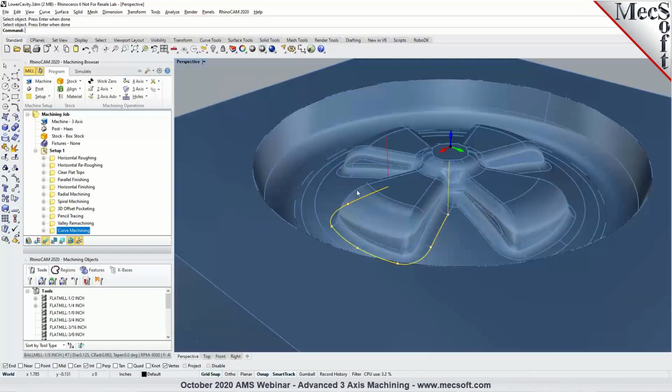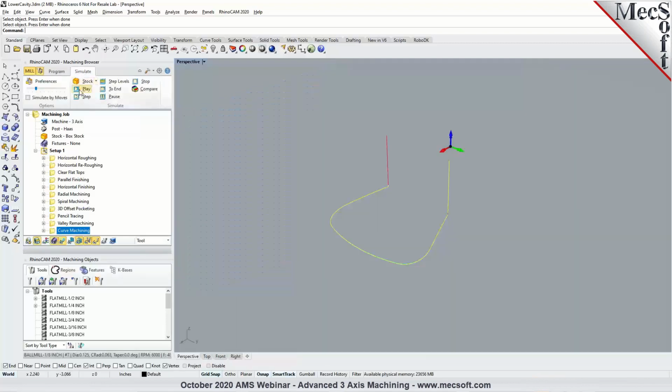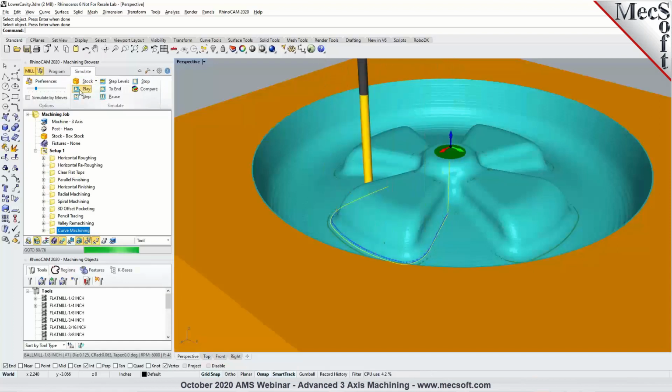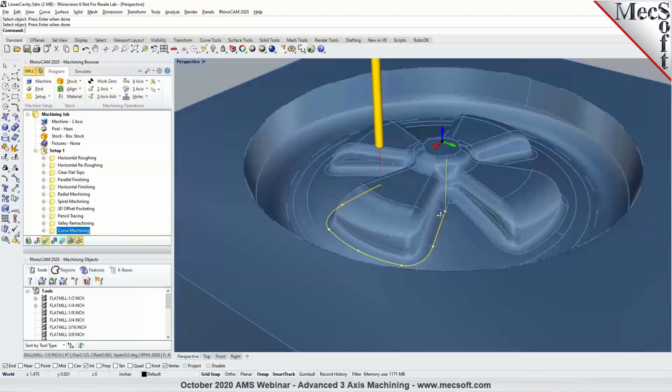That will basically eliminate some of that jaggedness in the toolpath with curve machining, because the curve is being projected to the underlying model, and the cutter path follows the curve, or stays on the curve, as you're trying to clean it up. And also I would avoid using any flat end mills or square end mills for pencil tracing operations. As Joe pointed out, you're going to end up running into this jaggedness on the toolpath. So try to use a radius tool, which could be a corner radius tool, a flat mill with a slight corner radius, or typically a ball mill cutter for pencil tracing and remachining toolpaths.